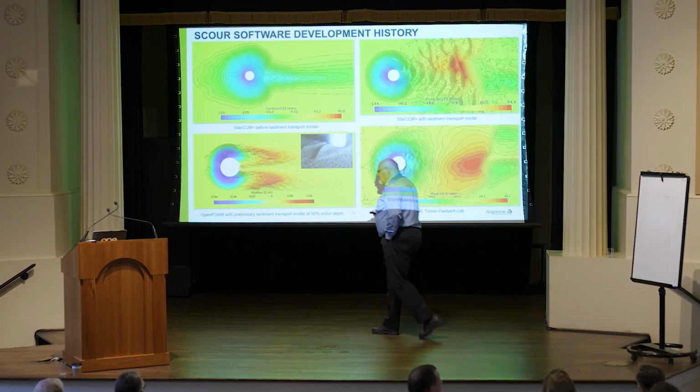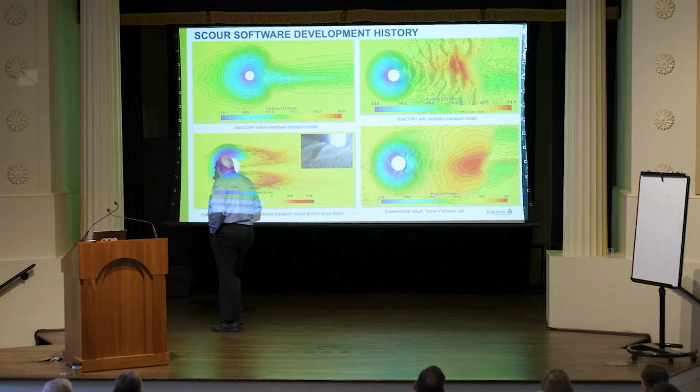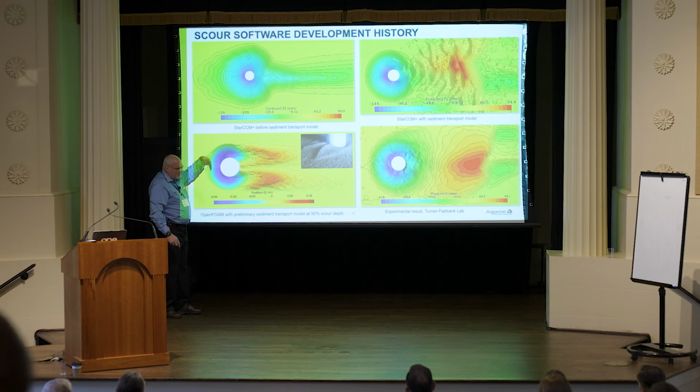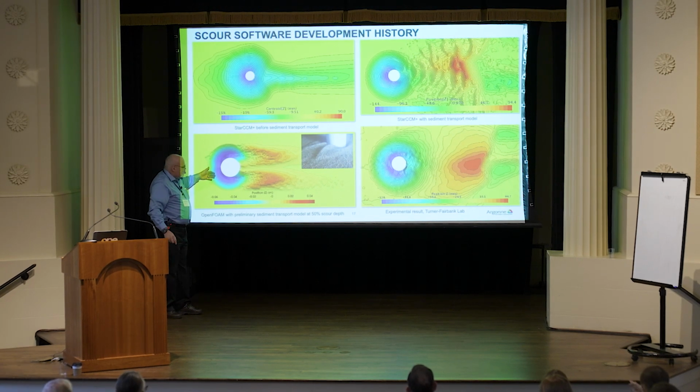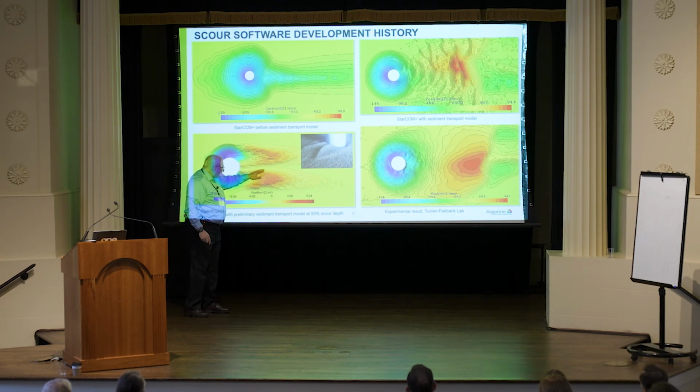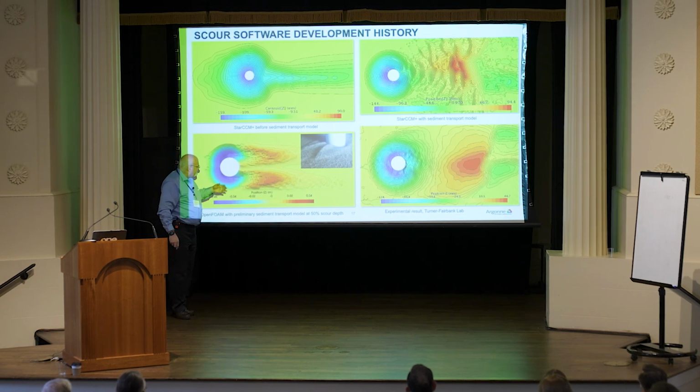And so our newest thing that we started with OpenFOAM, and I didn't run this very long yet, so the shape of the deposition is not final by any means, right? But what you see here is that when we dig to maybe 60 millimeters, the other one goes to 125, 130, something like that. So this is not the final stage. Maybe this is 25% into the case or so, right? We see these lobes forming here where the material deposits, right? So it took small time steps in the erosion scale, but this only ran for a couple of days or something like that.